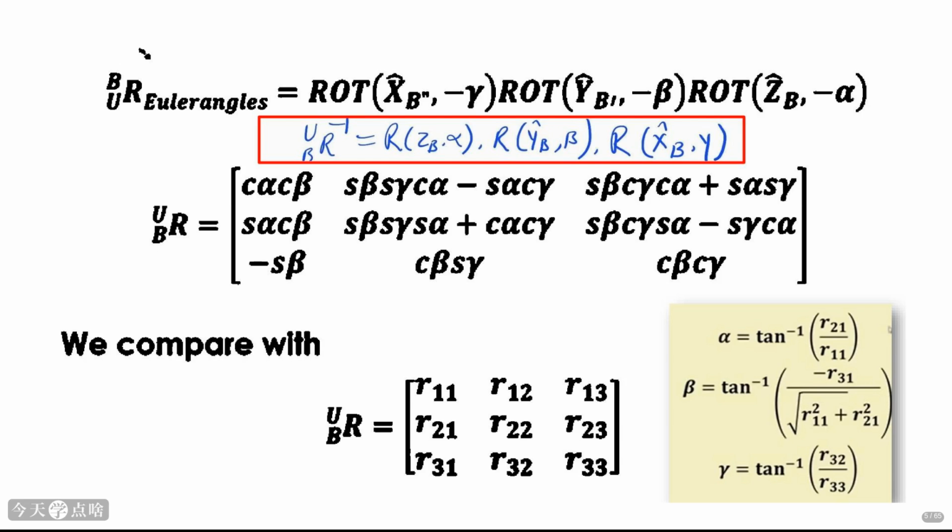For Euler angles, we typically use the z-x-z convention, meaning we rotate around z, then x, then z again. The formulas here show how to extract these angles using the tangent inverse function, just like before. Again, it's a systematic way to decode the orientation matrix into the specific sequence of rotations that produced it. Understanding these formulas is crucial for interpreting and generating orientation data in many applications.